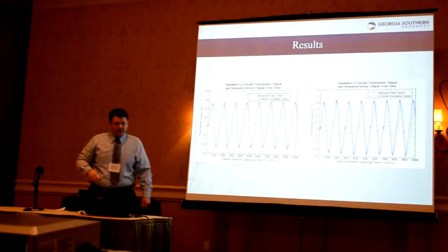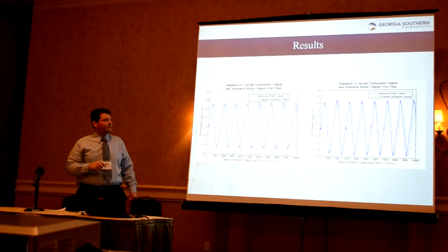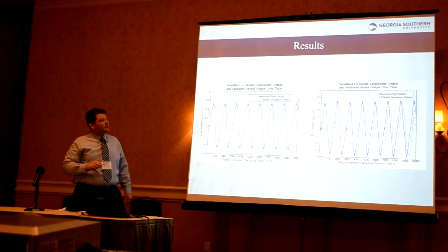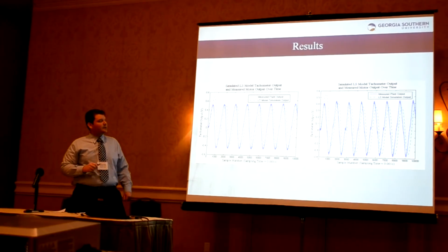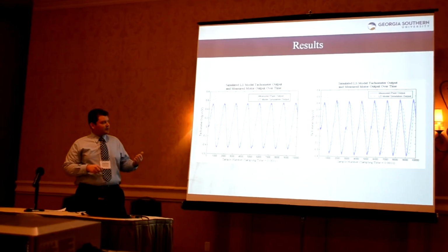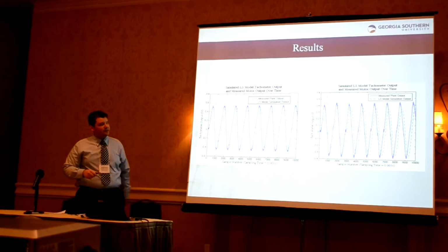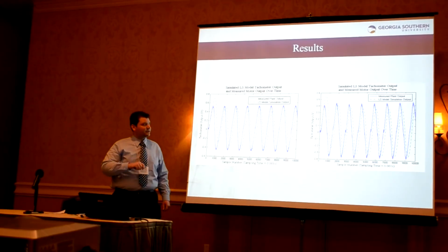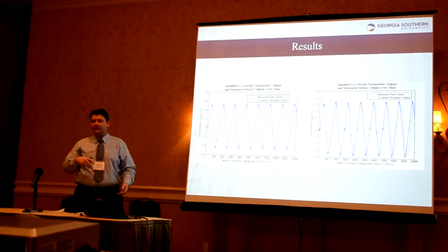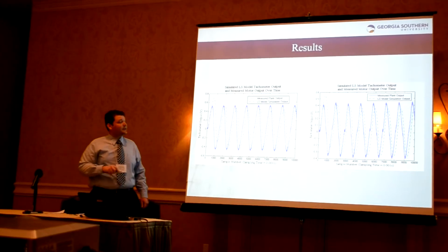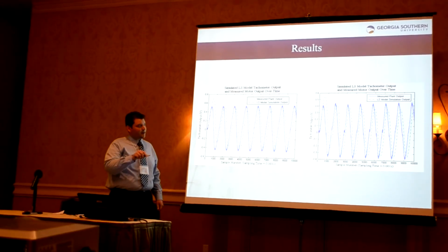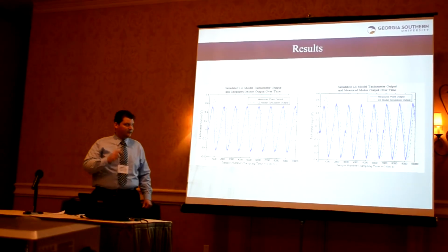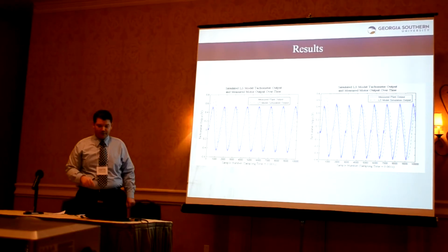Further along, you can see on the left, the 0.75 Hertz 3 volt peak to peak sine wave was used for the same simulation, and you get similar results for the higher frequencies, the 0.75 Hertz sine wave and the triangle wave on the right. There's slightly more phase shift caused by that initial problem with the dead zone effect, the higher order dynamics at the beginning. And you can actually see the dead zone effect more so in the actual DC motor response at the 0 point, the direction turn point.